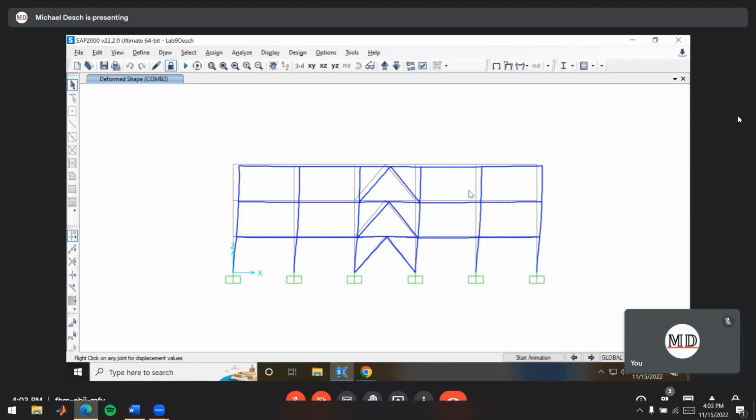Make sense to everyone? Okay, so that's deformed shape. You guys don't have to mess with the amount of deformation if you don't want to. It's just for your knowledge. If you do want to exaggerate something more or less in your model results, I would never exaggerate anything less than 1 times what it's actually going to deflect, because then you're kind of covering up how much it's deflecting. But it's good to scale it more if you're trying to see exactly how much it's deflecting. Yeah, user defined. I set this one to 500 instead of 100. That's what I'm getting here.